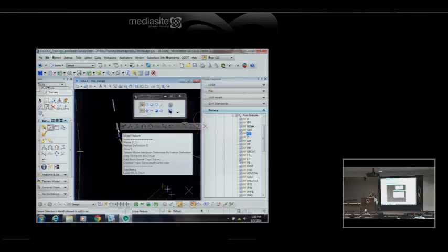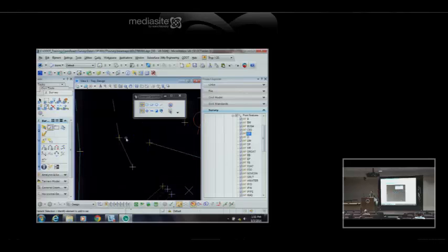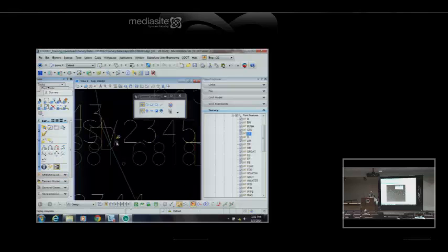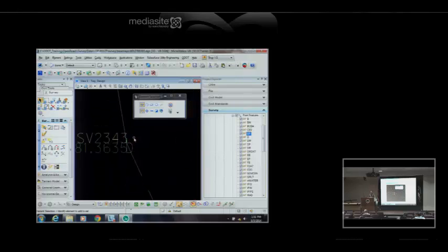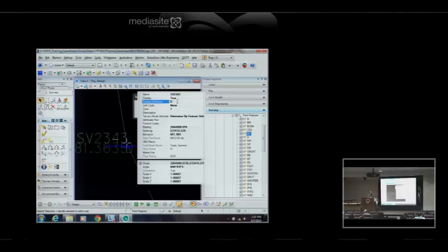Second type is a dynamic link. A dynamic link means these are connected, they're all the same feature code, and they're connected in the order that they're collected. And they're linked dynamically by the software. So, for example, this feature is, let me turn back on the display. This is a D for a ditch line. Set my text size smaller here, or my annotation scale. Okay. So I'm just going to pick this point that I can get. And in the point properties, I'm going to change it to an X, just because I can.